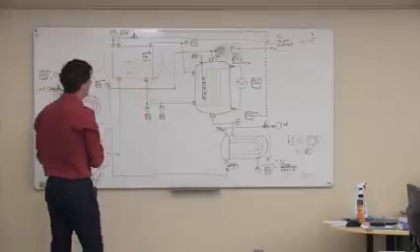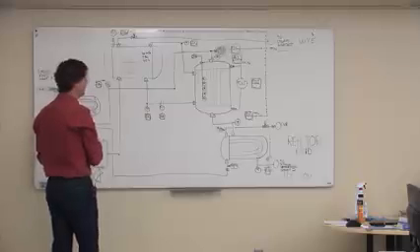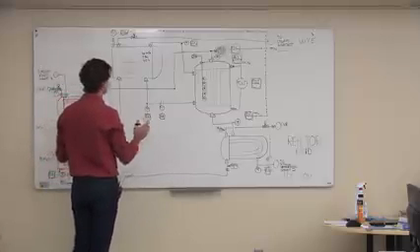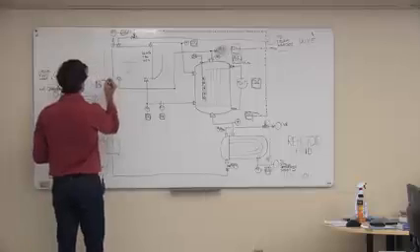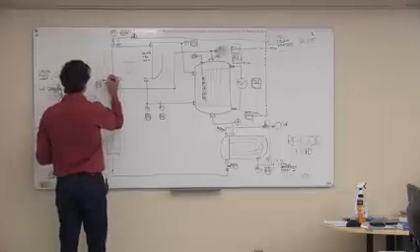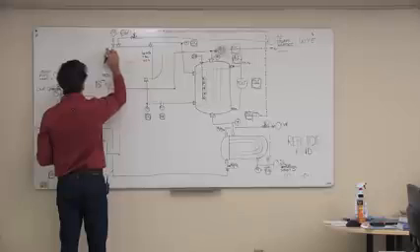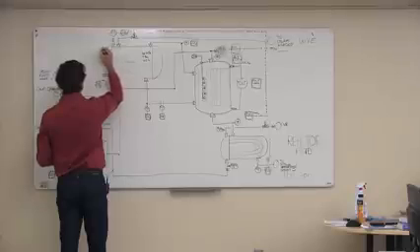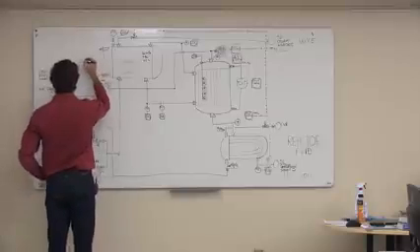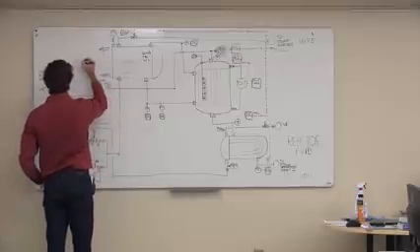So right off the bat, we know that we need to have a level transmitter and a level control of some sort. So let's put that on there right now. We need a nozzle. Probably going to have some valves. I'll tell you right now, it's going to be a 3-inch nozzle. Okay, let's draw the level transmitter out here so we give ourselves a little bit of space.